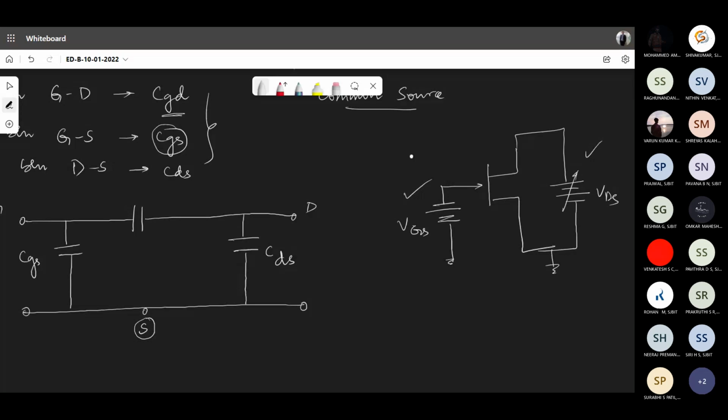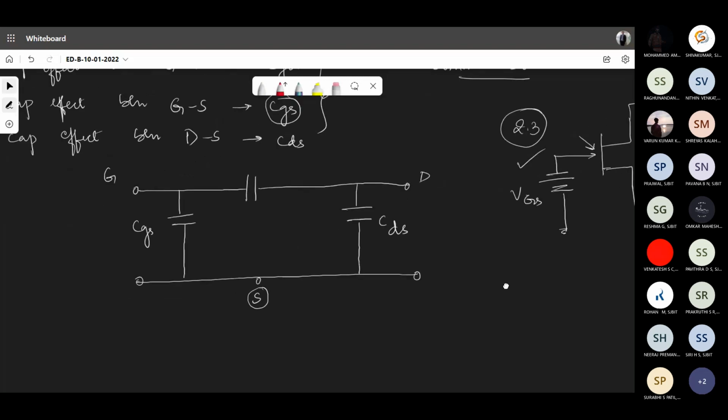In the laboratory, it was around 2.3 to 4 volts where you got the pinch off. Probably around 3.5 you got the pinch off. So this negative voltage, what you apply to the gate is lesser compared to the source negative voltage. So even there also you can see a kind of reverse bias coming into the picture. Okay. So there is reverse biasing everywhere.